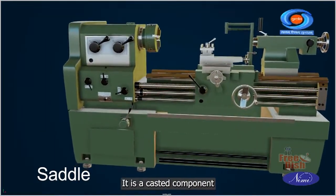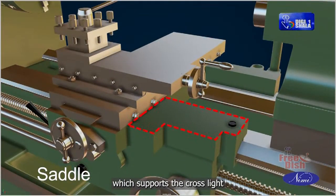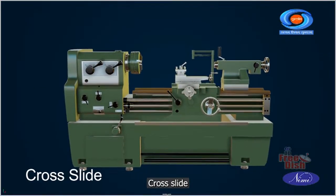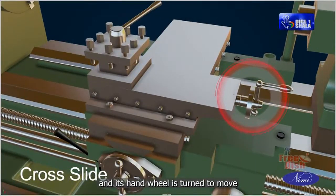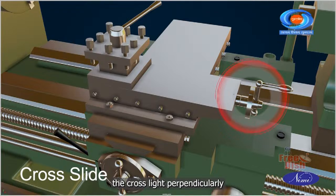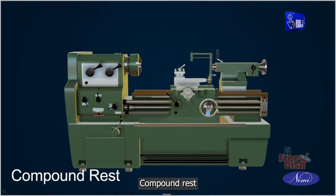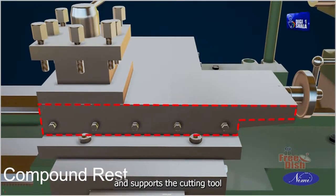Saddle. It is a cast component positioned on top of the carriage which supports the cross slide, compound rest and tool post. Cross slide. It is positioned on top of a saddle and its hand wheel is turned to move the cross slide perpendicularly to the axis of the lathe. Compound rest. It joins the cross slide with tongue and groove joint and supports the cutting tool and tool post.